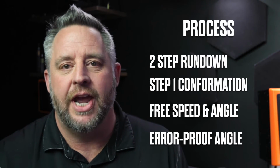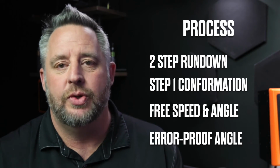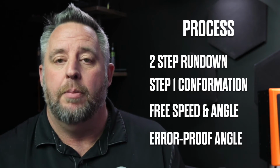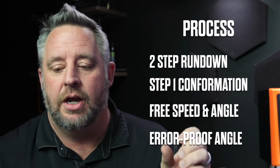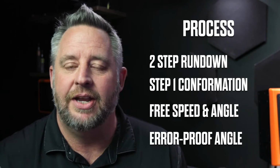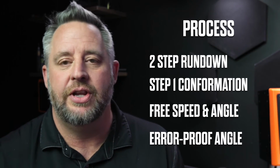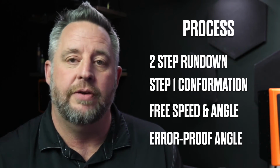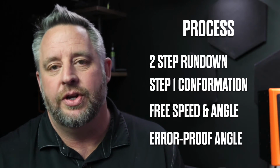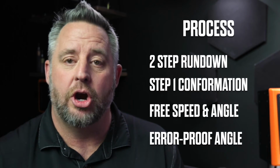And as we look at the process, that may be a little bit more clear, but what happens, especially with a long fastener at a lower RPM, is the rundown would take a while. For us to be as efficient as possible, we can increase the RPM for a certain number of turns within that fastener. And again, that's going to allow us to be more efficient and run the fastener down at a faster RPM.